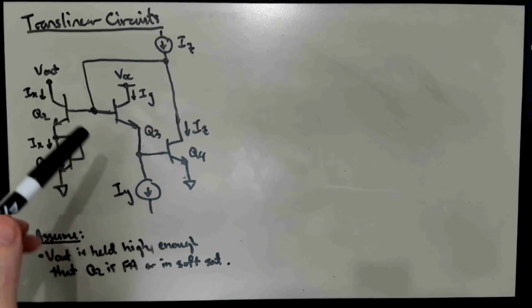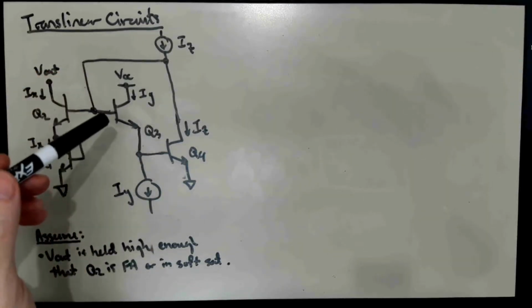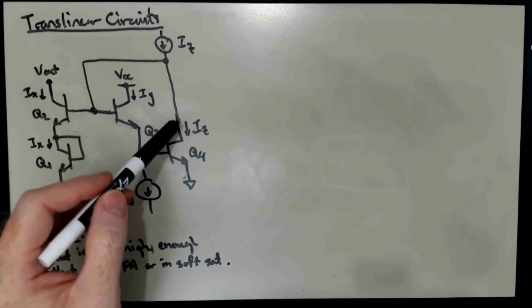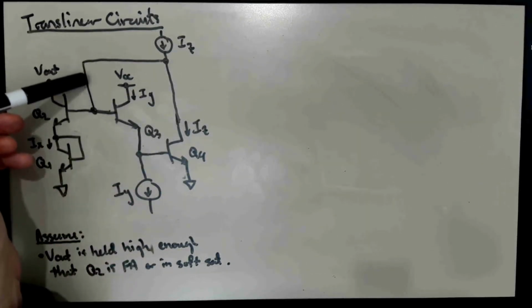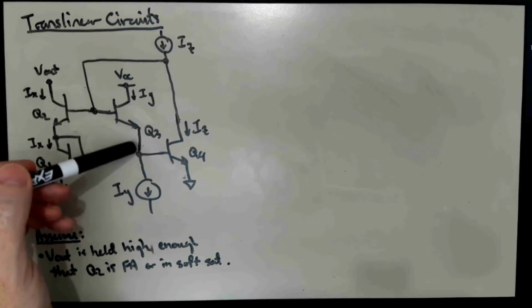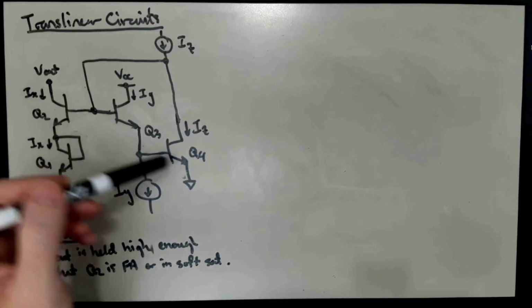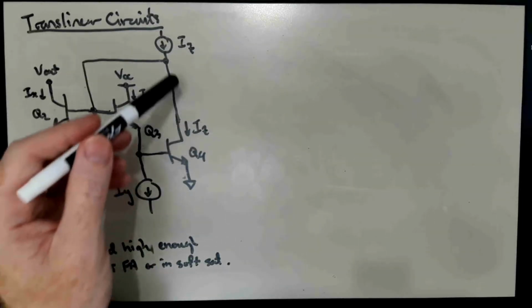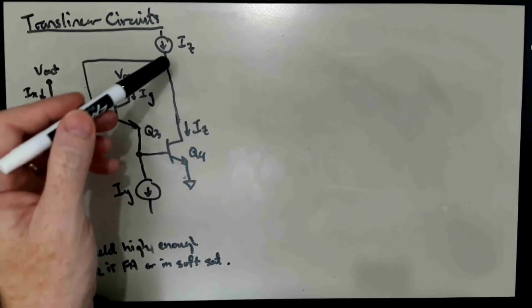And it doesn't really matter that there's the level shift there, because if this current is too big and this current needs to come up, what will happen is that this voltage will start to increase. That pulls up on the emitter, which follows what the base is doing. It pulls up on the base of Q4 and turns the current level up, so that the difference between the input current and this current in Q4 is reduced.